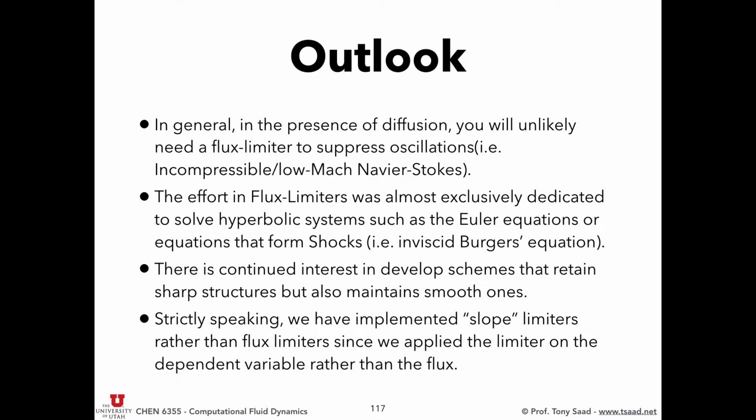With flux limiters, you want to limit in time, because you don't have the upwind value of the flux. You don't use that. The flux, you already have the value at the face, and you're computing the flux at the face. So you're going to limit the flux over time, because in the finite volume formulation, that integral of df by dx also has a time integral, from n to n plus 1. So that's where you limit the flux. It's a little bit different, but they're equivalent in a way. They'll produce the same results.